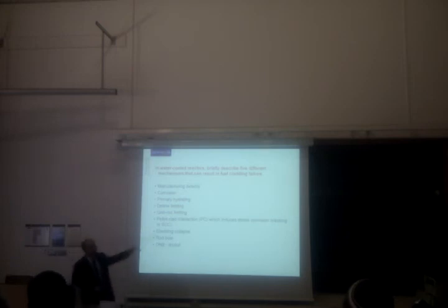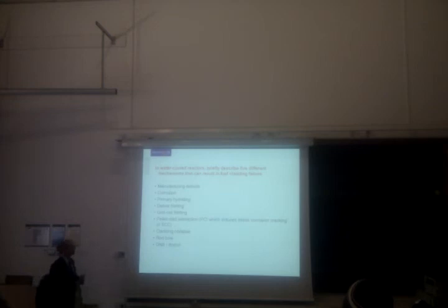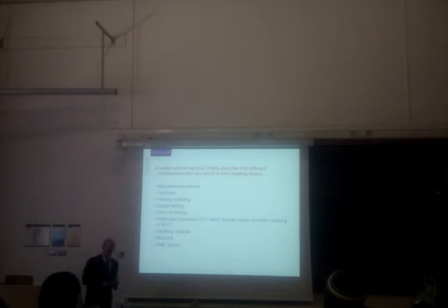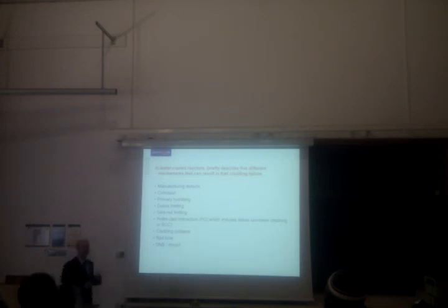Pellet cladding interaction is pretty much what it says on the tin. It's the interaction stresses between the pellet, which is relatively hard, and the cladding. That can be accelerated by the presence of corrodants, typically the halogens, and unfortunately for us we get quite a bit of iodine produced. So iodine tends to accelerate that cracking corrosion mechanism.